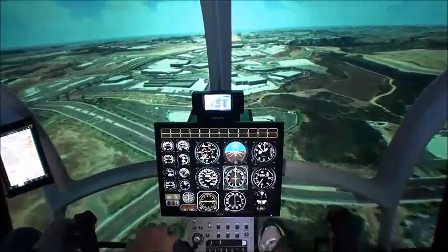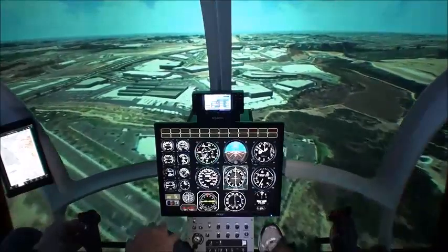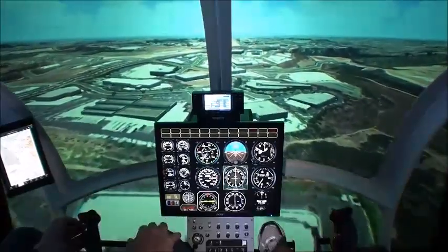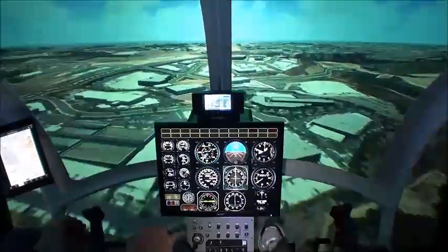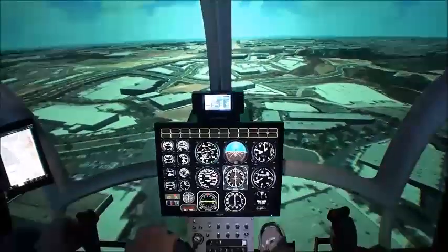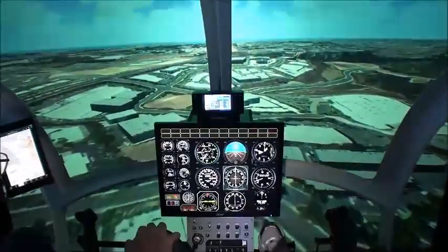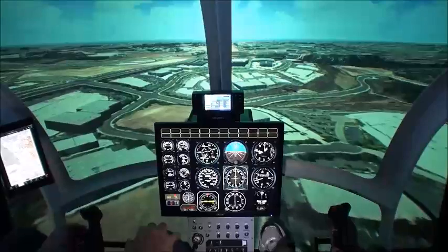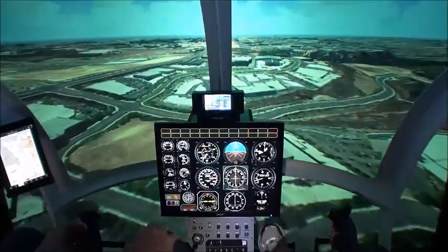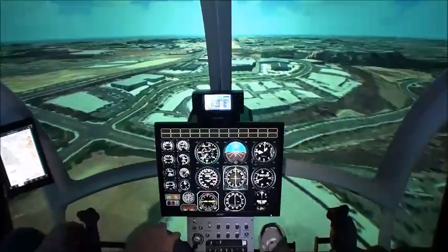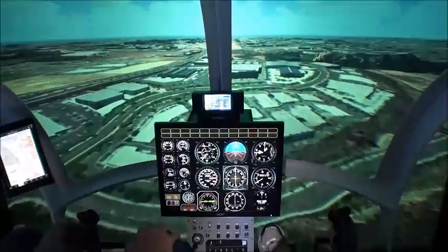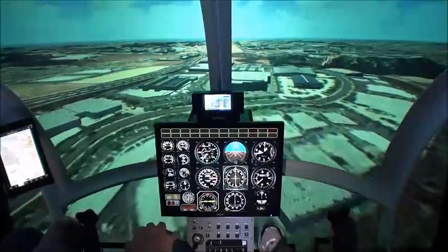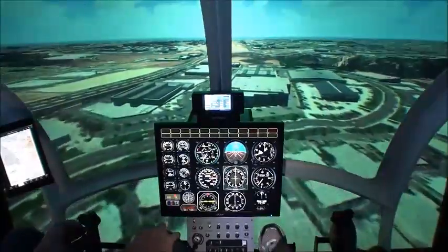Straight ahead on the localizer to 3,000 feet, and then we're going to intercept 325 inbound to Oceanside, and I'll tune the radios if we need to. Okay. We're 500 feet above the field, and we're going down to 737 feet.